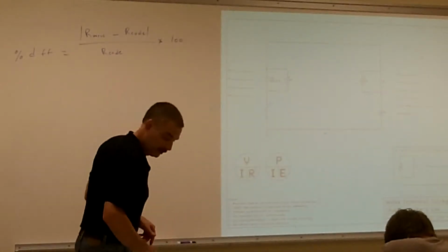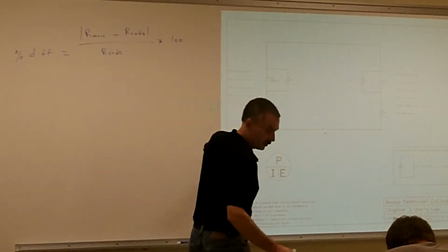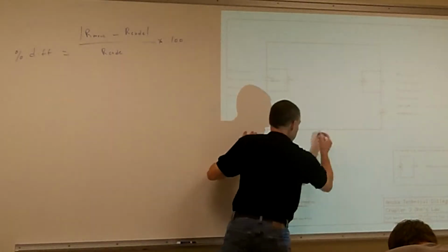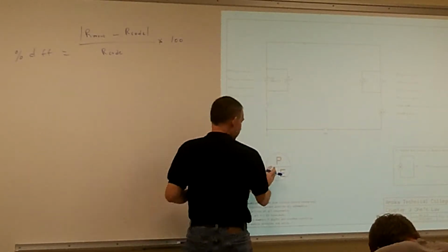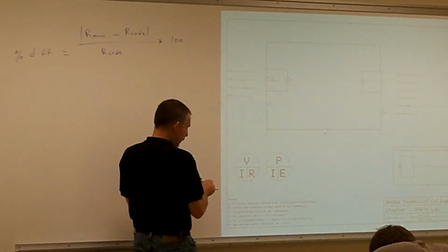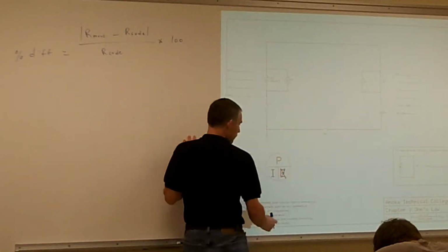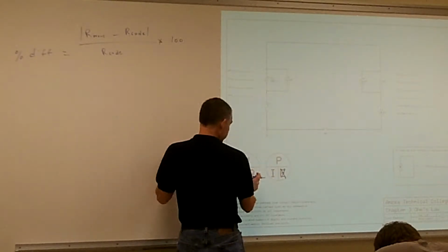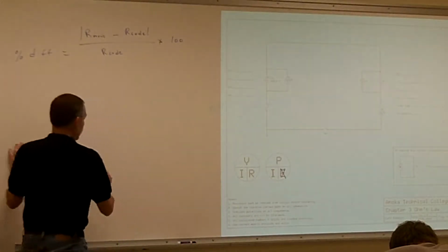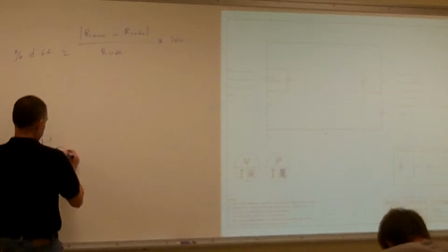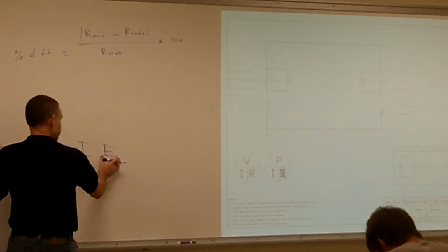That's how we calculate power. Now, that pie chart that I just handed out, or that's on page 103, is derived from only these two formulas. For example, let's say I wanted to find power, but I don't know my voltage, but I do know my current and my resistance. So I can substitute into the formula. P is equal to I times E, and I can go ahead and substitute for E.